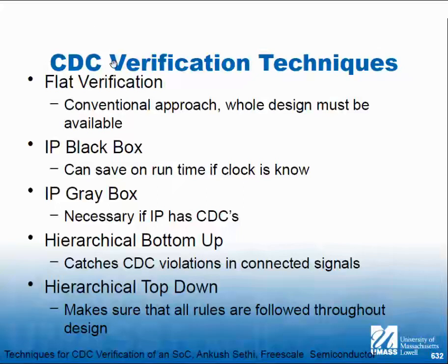Now, here's the thing. You run the tool, and it comes up with 4 places where there's a clock domain crossing. And you say to the designer, there's 4 places where there's a clock domain crossing. And the designer says, oh, I don't care. The timing is such that that will never be a problem. And you don't just waive it, because it's always a problem. No matter what frequency you're running at, no matter what the disparity between those two frequencies is, if you get into a metastable state, it over time will propagate into the design and cause another problem.